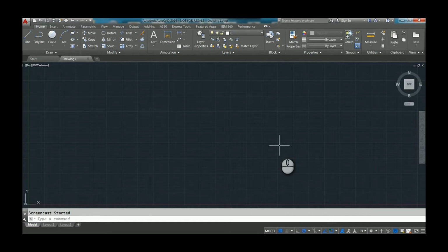This month's tech tip, I'm going to show you how to restore your AutoCAD profile, or I guess AutoCAD CUI, to classic mode. I'm going to show you a couple of processes here. Basically, one is by bringing over a CUI from a previous release, such as AutoCAD 2014, and the other way will be creating it from scratch from the AutoCAD 2016 software.